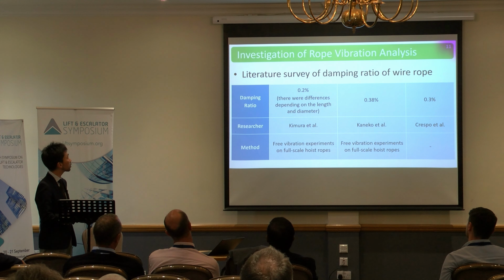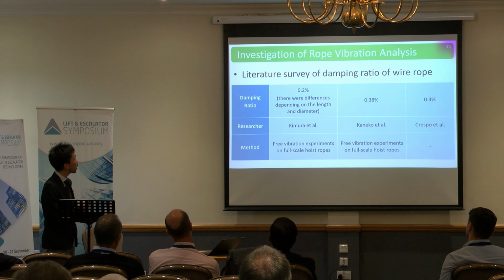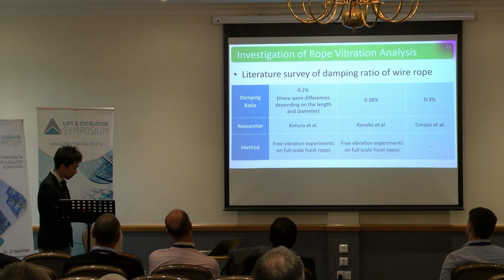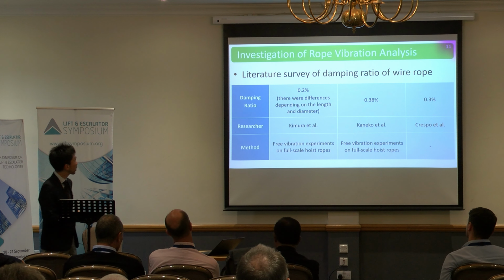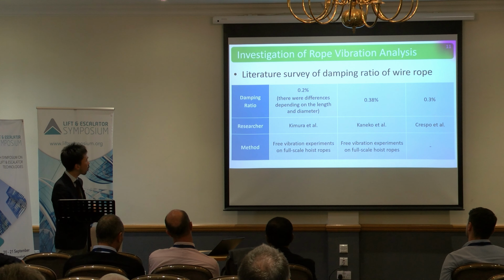We also did another literature survey regarding the damping ratio of wire rope, and we found that wire rope has only 0.2 to 0.4% damping ratio. So this is a very small damping ratio.